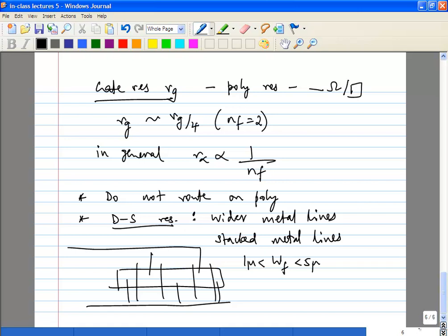Okay, try to keep it somewhere in between these two: 1 to 5 microns. If you have very large transistors, you would probably want to tend towards the larger limit, towards 5 microns. Otherwise your aspect ratio will get very weird. If you have very small transistors, let us say the overall width is only 10 microns, you're not going to gain a lot by making it into 1 micron fingers. You'll get a very long finger again. So you probably want to have a trade-off, but keep it somewhere in between these two numbers.